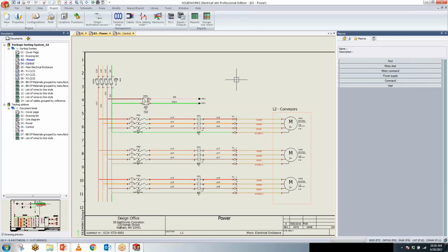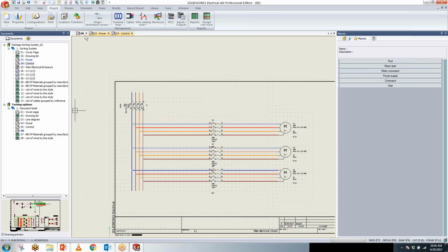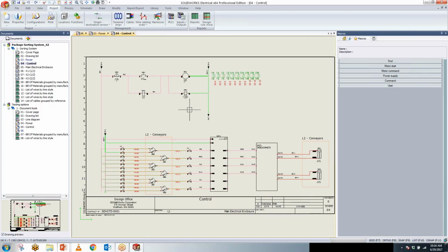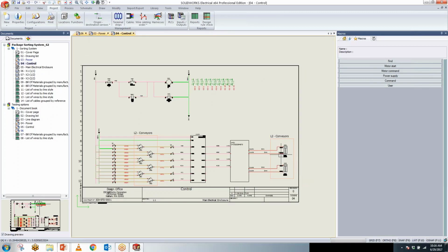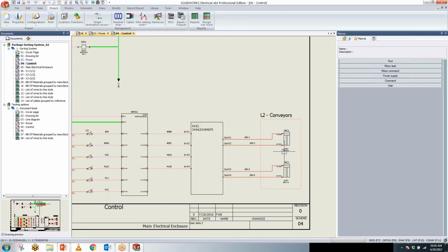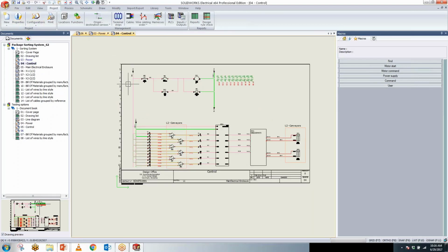The next step, we're going to take a look at how we can reuse our data. Like I showed you before, in my example schematic over here, I was able to copy and paste components, so I didn't have to do that again and again from scratch, saving me tons of time. I can do that with macros, like I mentioned in the control schematic here. For example, that macro was stored in the library. It was created from scratch in another schematic, and then it was stored in the environment itself. It was archived and then reused and imported.